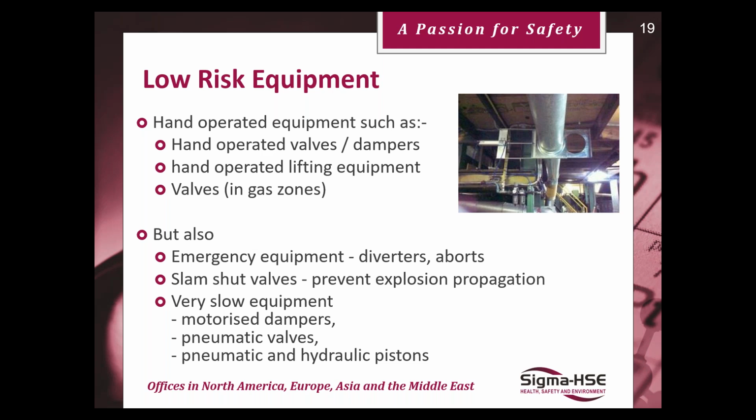And also to note that sometimes undertaking NIRAs would mean you have more focus on your maintenance procedure, and it's much more closely scrutinized. But there might be some equipment, say for example a small solenoid valve, where it's better to replace it with ATEX rated equipment in terms of costs than to undertake a NIRA on it, if it's just easier.